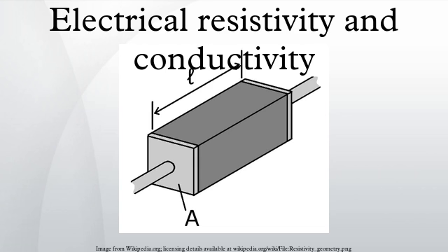The conductivity of a solution of water is highly dependent on its concentration of dissolved salts, and other chemical species that ionize in the solution. Electrical conductivity of water samples is used as an indicator of how salt-free, ion-free, or impurity-free the sample is. The purer the water, the lower the conductivity. Conductivity measurements in water are often reported as specific conductance, relative to the conductivity of pure water at 25 degrees Celsius. An EC meter is normally used to measure conductivity in a solution. A rough summary is as follows: